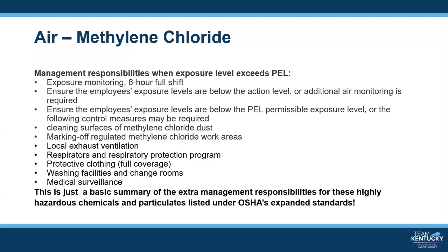And since methylene chloride is in the expanded standards, it requires extra responsibilities for management when the exposure level exceeds the PEL. It requires exposure monitoring of the employees for an 8-hour full shift workday. If the exposure level exceeds the action level, then additional air monitoring is required. If the exposure level exceeds the PEL, then additional control measures will be required.